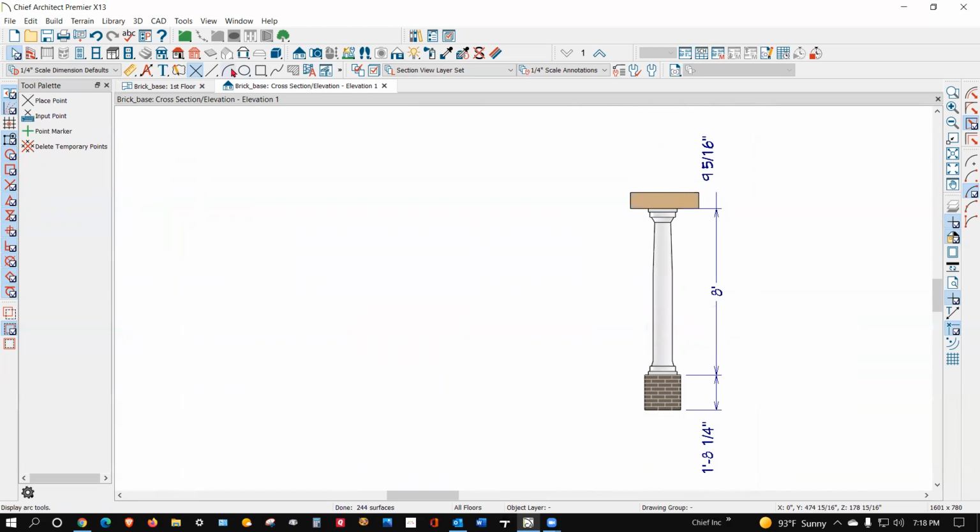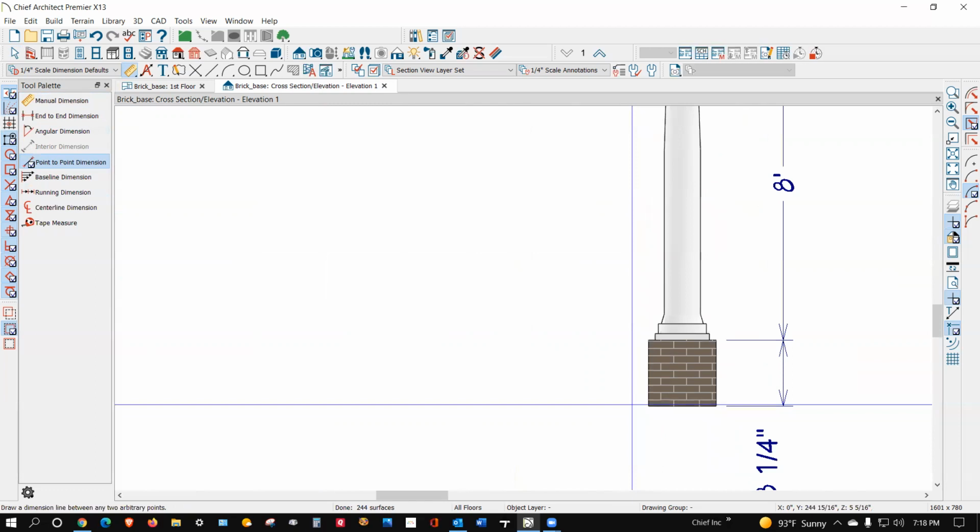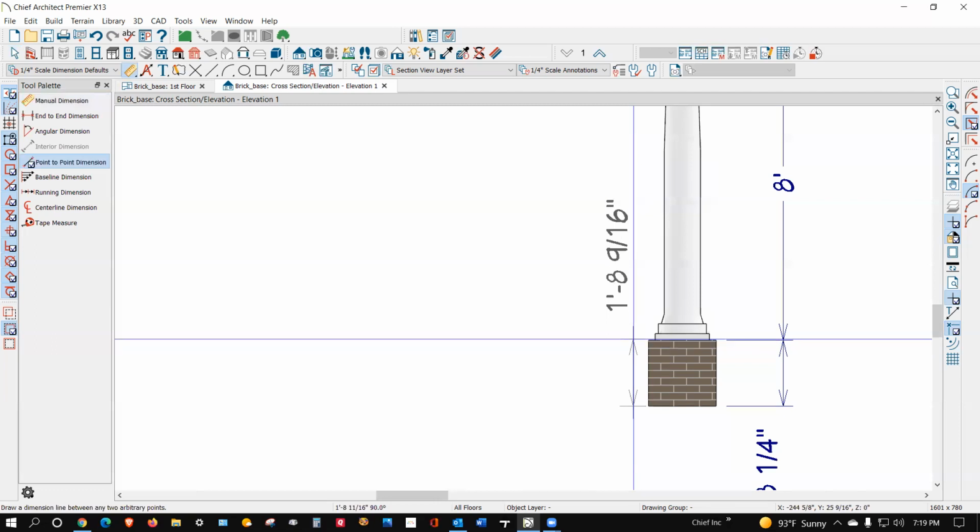Okay. There's also a tool called, now this is interior dimensions, for like between walls in plan view. And this will give you a display of the angle between two lines in elevation or in plan view. I mainly use it in plan view, but it can be used in elevation. And this tool here creates its own points. See, I'm going to line my cursor up there and then left click drag, and then get it exactly where I want it and then release the mouse.